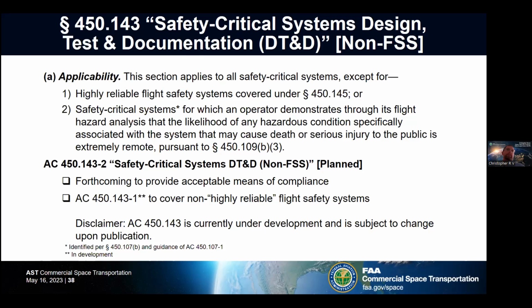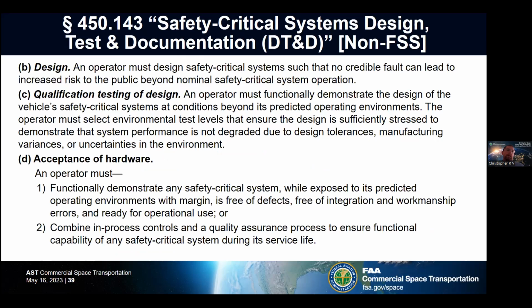143B discusses design. An operator must design safety critical systems such that no credible fault can lead to increased risk to the public beyond nominal safety critical system operation. 143C discusses qualification testing of design. An operator must functionally demonstrate the design of a vehicle's safety critical systems at conditions beyond its predicted operating environments.